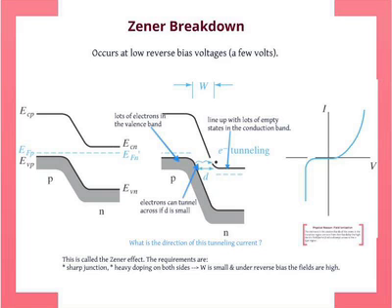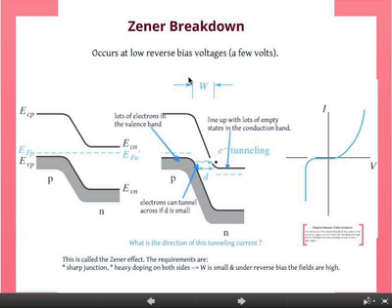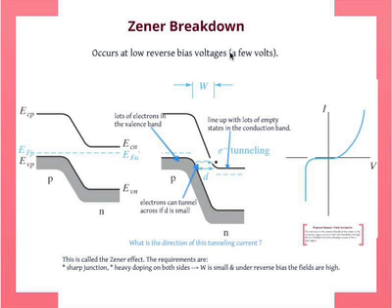Now, of course, when the barrier is smaller this way, the probability of tunneling is higher. In our case, that distance is basically determined by this W. The smaller the W, the higher the probability of this tunneling happening. Of course, if the energy barrier is smaller, you also get a higher probability, but you can't have much control over that at this stage. Okay?